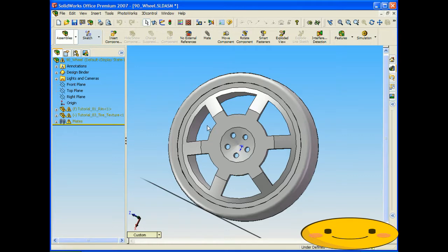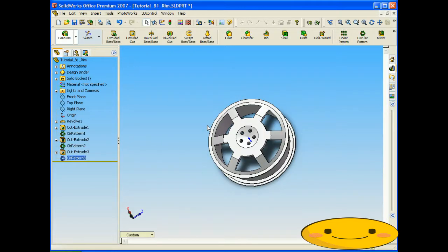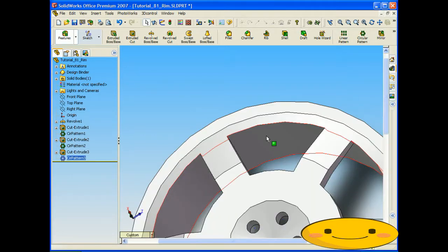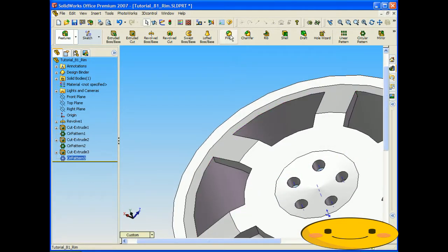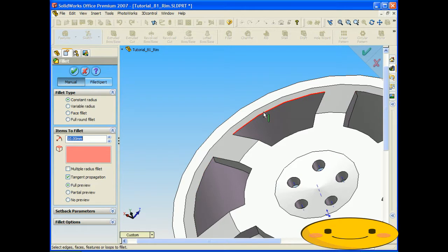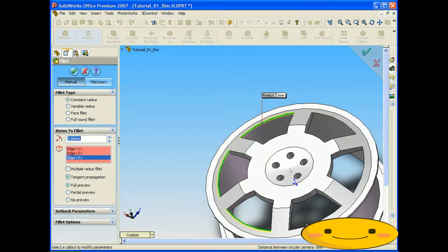Now let's flick back to the dish here, and we're able to make fillets and chamfers if we want all the way around. So around these edges, let's make some little fillets. So let's make them 3 mils. And let's make it go all the way around. Do each one. Click OK.